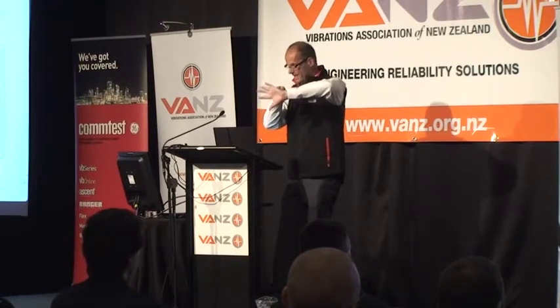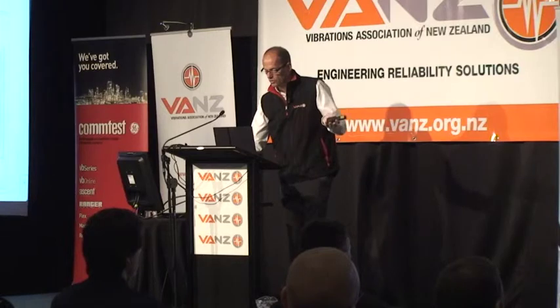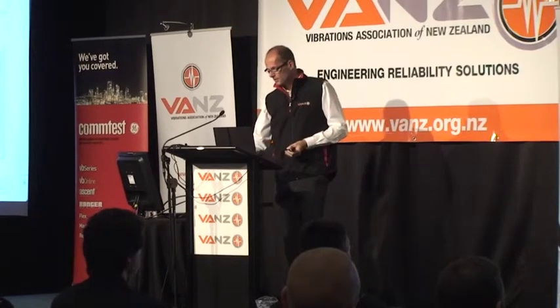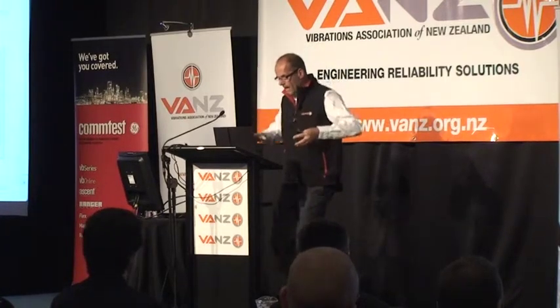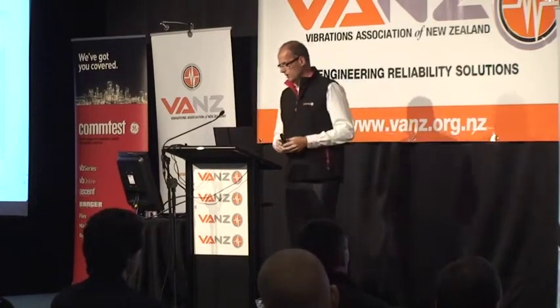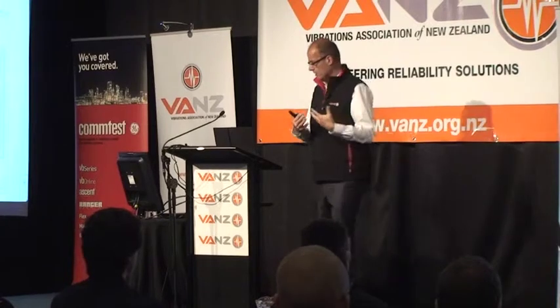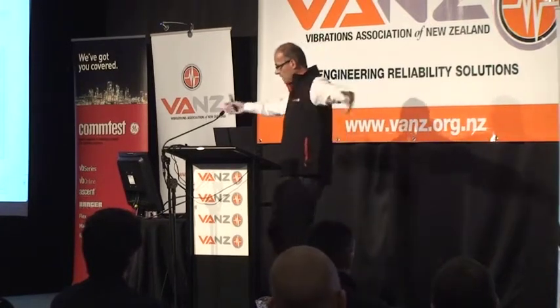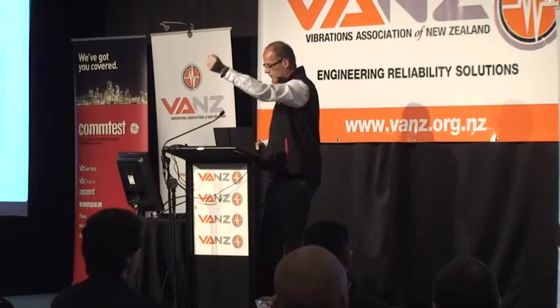We can see that actual displacement, whereas the most common sensor we'll use is an accelerometer, and it's sensing the acceleration of the bearing housing itself. So you put it on, and the bearing housing is moving in response to everything that's happening in the machine. And that's one of the places where people can get caught out. There's a feeling that no matter what happens anywhere in the machine, I'll be able to sense it if I just place it on the one bearing.